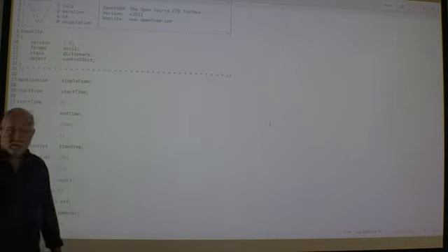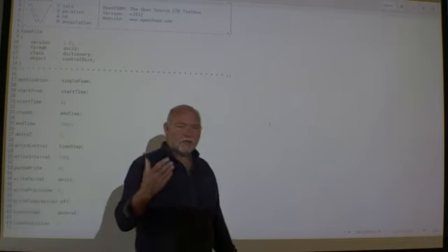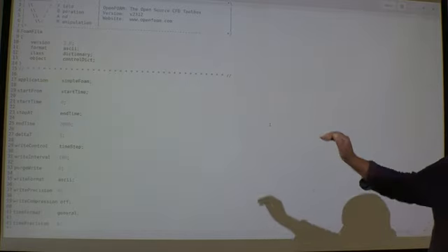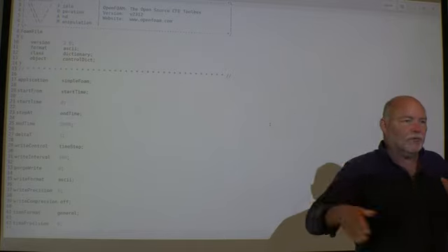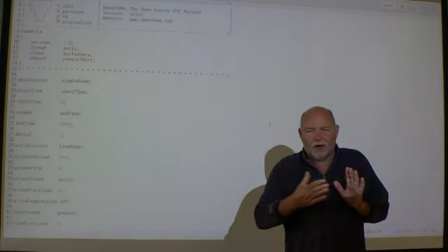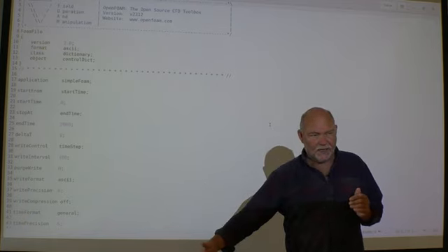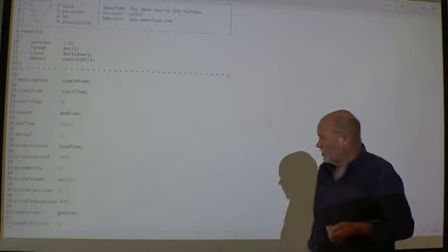This is a hint. simpleFoam is a steady state solver. It doesn't solve in time, but it uses time as an iterative dimension, so you don't get the real time history here. You're not interested in it anyway. I want a steady state solution and nothing more.